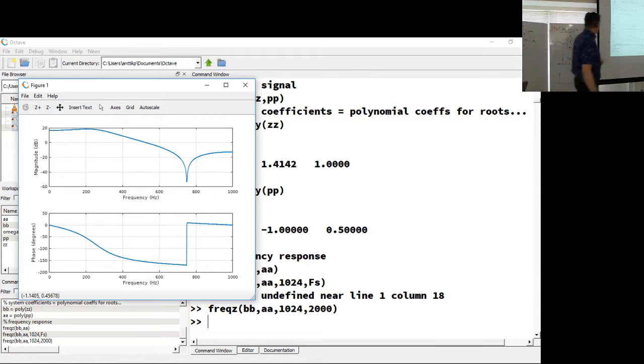Now we have frequency in hertz. So if you know your sampling frequency, use it on all of those plots. 2000 hertz gives you the Nyquist frequency at half of it. So 0 there, and we have the notch somewhere at 750 hertz. Excellent. And we have some gain at 250 hertz. Nice, just like I designed.